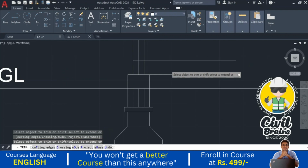I just go to the offset command, that is 0.6 and 0.6. Okay, I just extend these things using the extend command, and the remaining part I just trim. So now this is the width of the foundation, or width of the trench. I just write here, or trench. Okay, so now we just draw the footing.